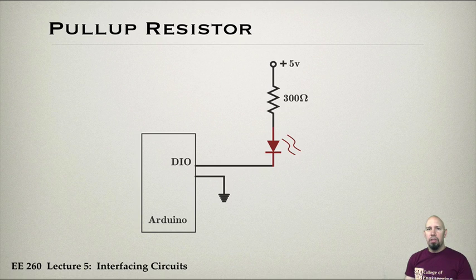Okay, very important in terms of, remember, the outside world is still analog, and so that's why we have to throw in resistors and stuff like that. Sometimes we'll throw in capacitors and other things because they're important. Now, remember, a resistor has a constant resistance. A capacitor actually does not have a constant resistance. It depends on what's applied across it as to what resistance it has. But you can think of a capacitor as being a DC open circuit and an AC short circuit. That's one way of thinking about it.